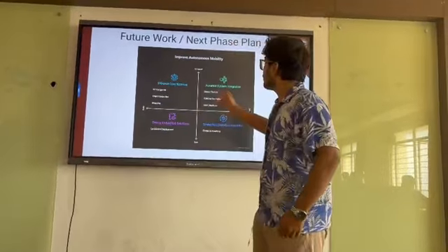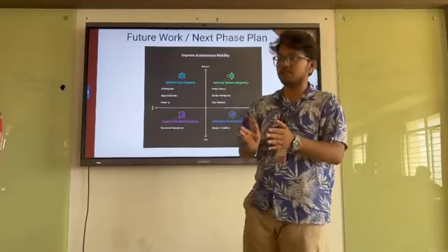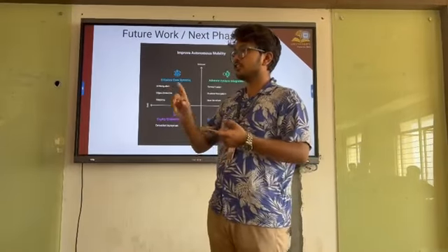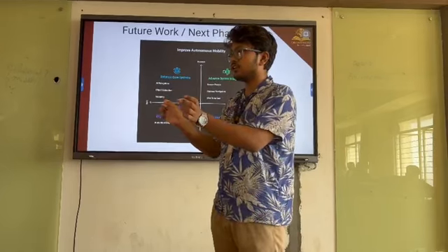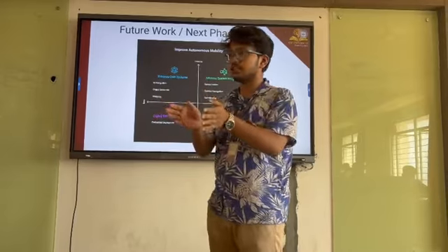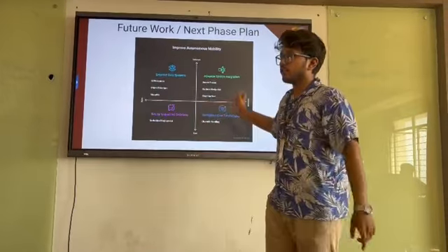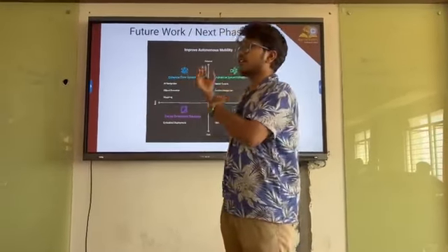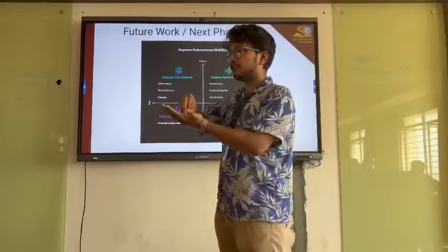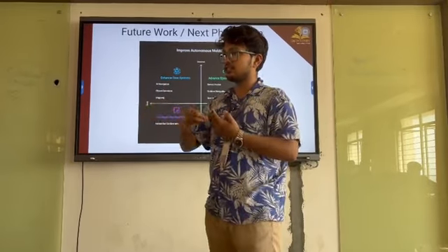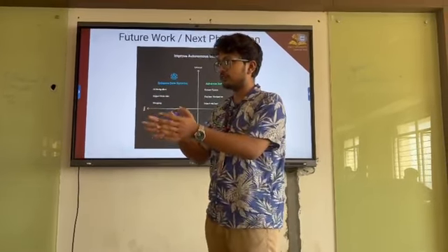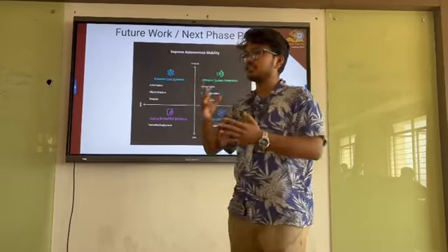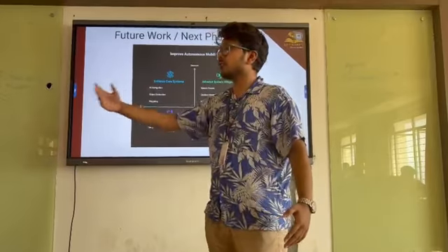So then we are going to use sensor fusion. In sensor fusion, we are going to use two cameras instead of one camera. Stereo vision, in which we use two different cameras, left and right, which detect the images. Then monocular depth estimation is another one. We are going to calculate the distance, image depth estimation, then the actual distance estimate, and combine those things, mapping. For example, the MiDaS value is 200 and the distance is 20 centimeters or 20 meters.